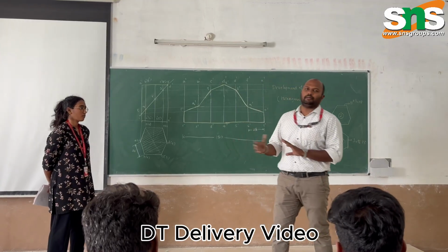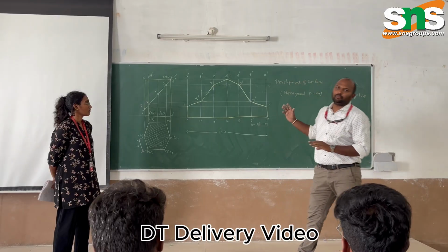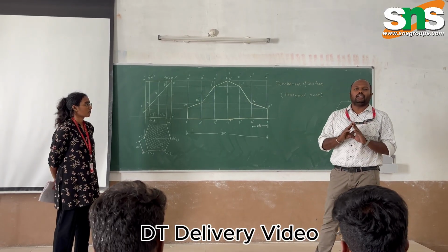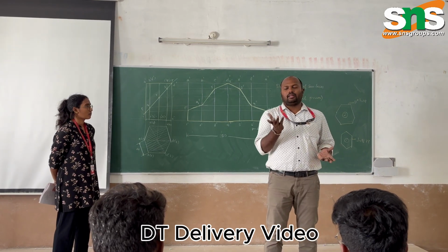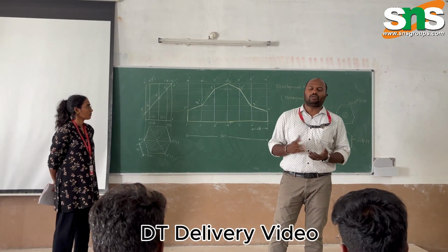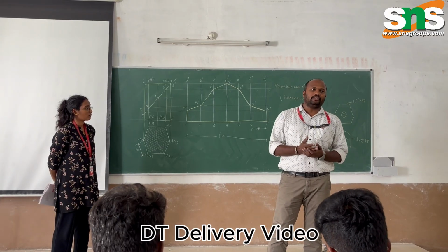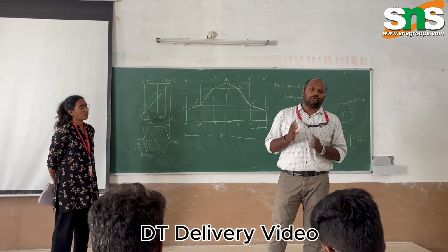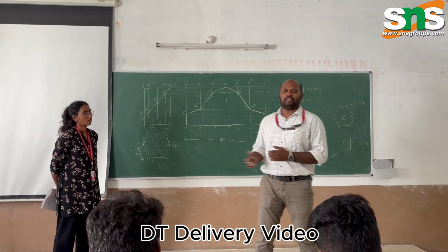But in today's class we are going to see the development of surfaces, where we are going to develop a particular solid, maybe a prism or pyramid or hexagon or cone or cylinder, and therefore we are going to introduce the cutting plane. After cutting the particular solid, we are going to develop it.